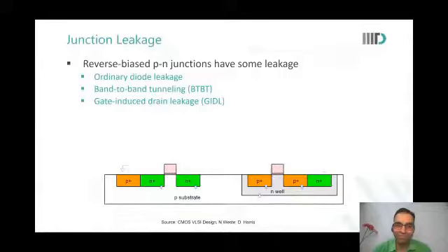So in every P well I can connect to ground and different. It's a huge area penalty. Huge. So you do not do it for digital circuits. This is only done for analog RF circuits, not for digital circuits at all. It's a huge area penalty.